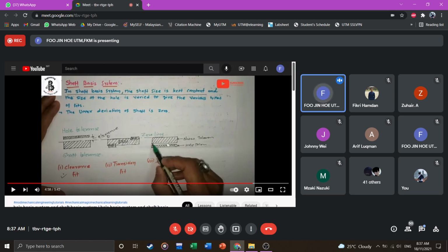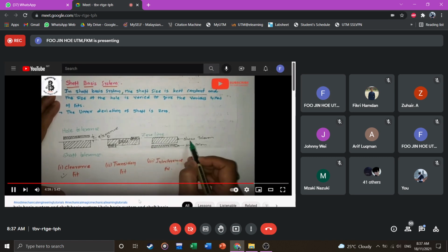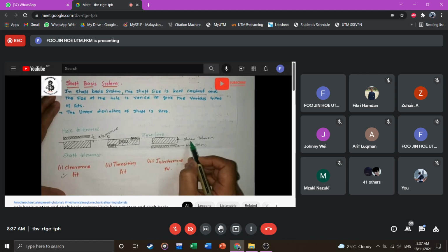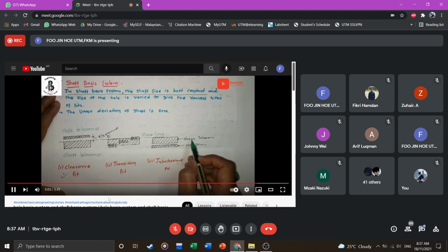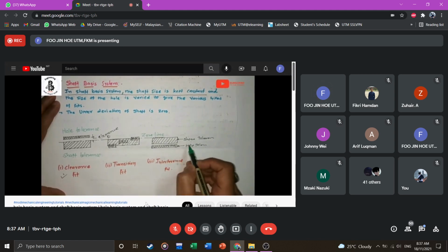The hole tolerance means that it's always a tight mating, or tight assembly. The shaft tolerance we already described like this will be kept constant, and we just change the hole. So if you find the hole tolerance below the shaft tolerance, that will always make an interference fit.